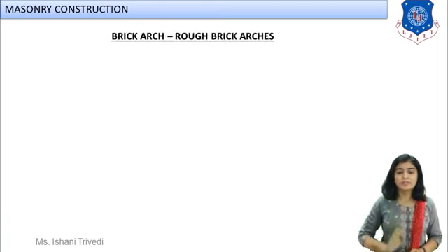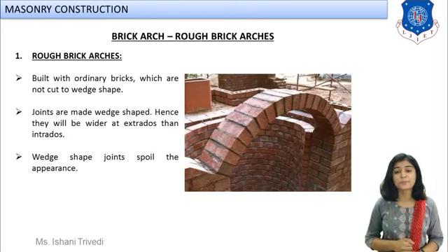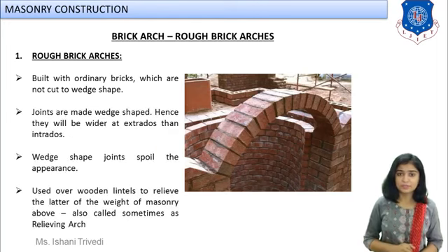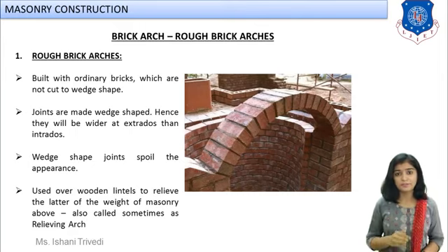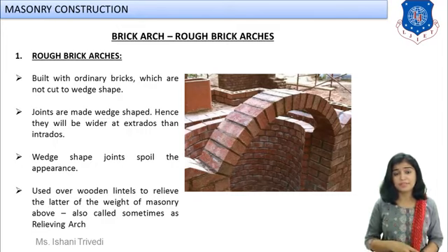Now let us discuss the classification of the arch. As I told you, brick arches will be further subdivided into three categories. What are those categories? In the brick arch, the first classification we have is rough brick arches. Now look at the image flashing over here. Can you see that the bricks are not cut to a proper wedge shape? They are not properly made into the shape of voussoirs, right? They are somewhat used in their natural condition.